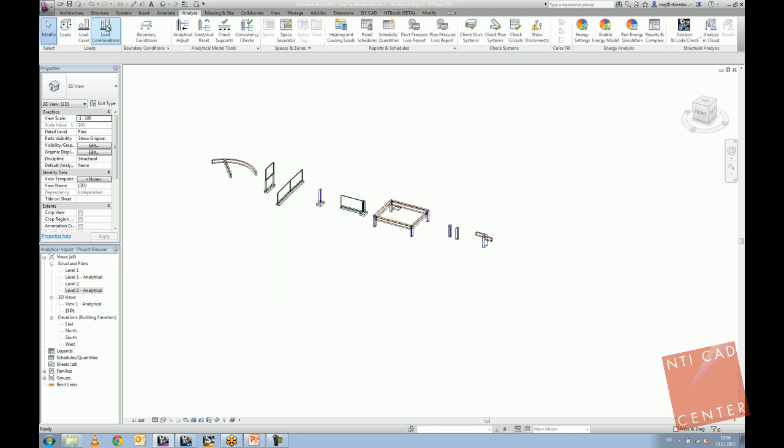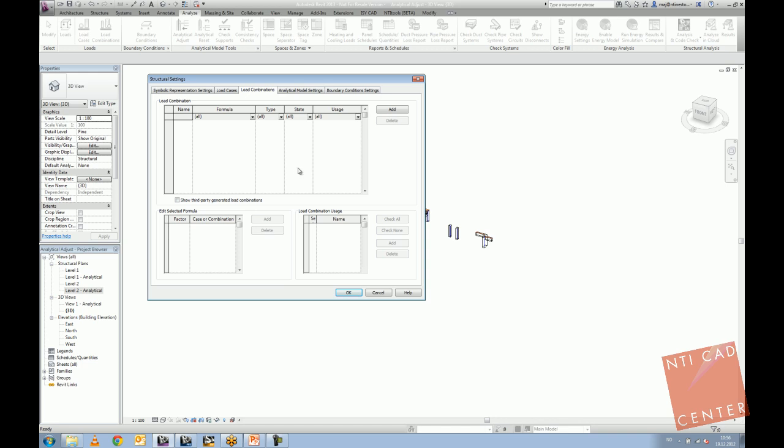Load combinations. Basically, when you have defined your loads, you can define a new combination. For example, I'm not specifying a name, just saying that this combination will be made from dead load, live load, and then maybe snow, and then maybe something else like wind, and then I'm specifying the factors manually. 15 is a bit too much for dead load, don't you think so? So 1.5, specify a number, for example. So that's the way how you compose the combination.